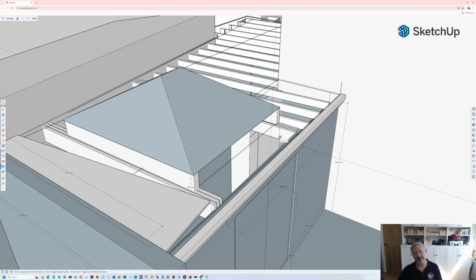Yeah, 175. So a triple beam of 175 millimeters, and that will support the roof light. And then we'll have another triple beam of 2.2 on this side, which doesn't have the benefit of the support a third of the way along the length. So I think this will be as strong as this ultimately. So that's the idea.